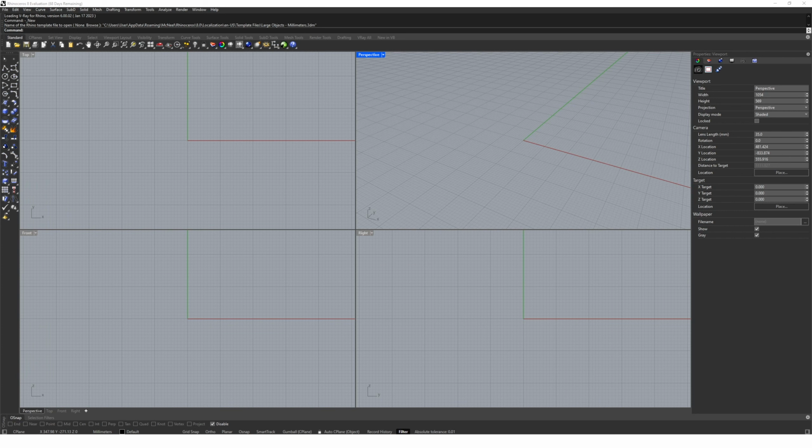Let's write our first command in Rhino. I think we should create a box to begin with, so let's type in box. You can see Rhino gives you a list of commands with the word box in them beneath the command line, almost like a search function. If you want to do something in Rhino, it's worth sometimes just typing in and seeing if a command exists. Let's select box and our command line will update.